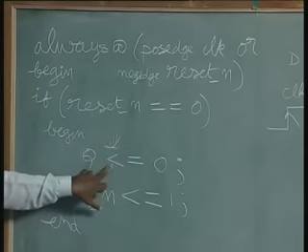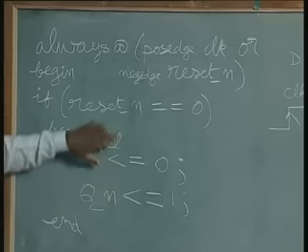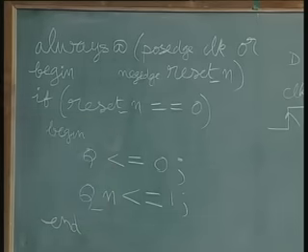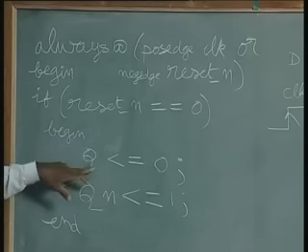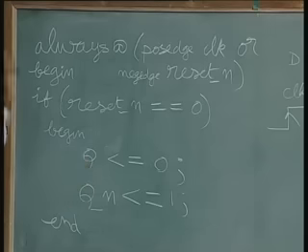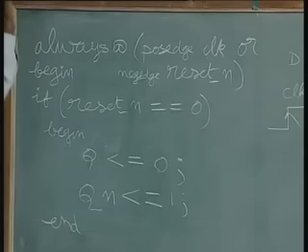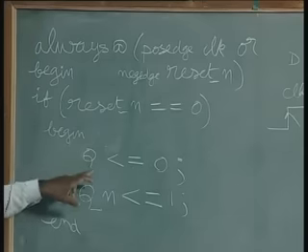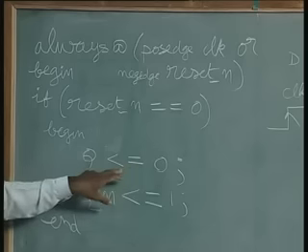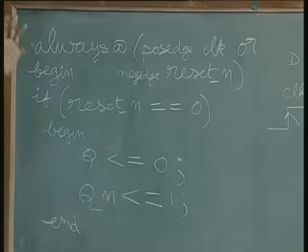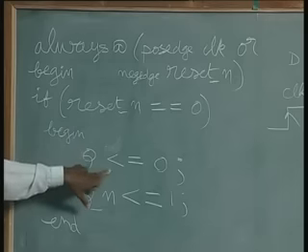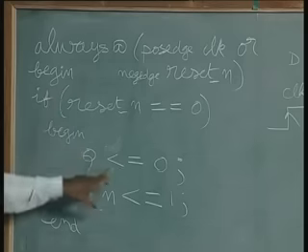It is not less, you have to read this together. So, this is equal to this distinguishes assign statements and this. In assign you had used plain equal to, all combinational you use that, and here you have to use what is called a non-blocking statement. The earlier one is called blocking statement. And if you do not put this one, again the tool will complain. So, take care of this.